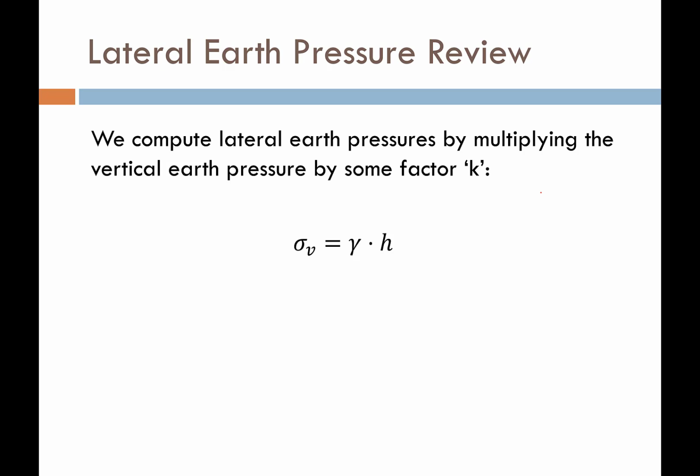So here's a review. When I talk about vertical stresses in the soil, this is what I'm talking about. I have a vertical stress in the soil, and it's the unit weight of the soil times the thickness or the depth of the soil. That unit weight times the depth gives me a pressure, and that is the vertical pressure. It doesn't necessarily need to be the effective pressure in this case, but if I'm computing lateral earth pressures, then I want to deal with effective stresses. For more information on effective stresses, go on my office hours page to my CEEN 341 class, my introductory soil mechanics class, and look for the lesson on effective stress, and that will help you out.